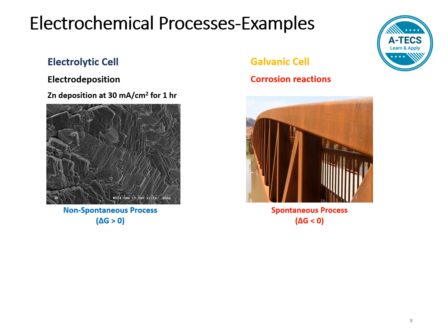On the other hand, material degradation due to corrosion is a spontaneous process because metals, which stand at a high energy state, tend to release a certain amount of energy and convert back into their lowest energy states. This cell is a galvanic cell, and the process is spontaneous in nature. That is why we always have the Gibbs free energy difference in negative.